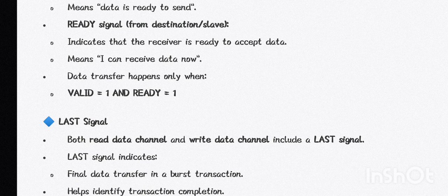Last signal: both the read data channel and write data channel include a last signal. The last signal indicates the final data transfer in a bus transaction and helps identify transaction completion.